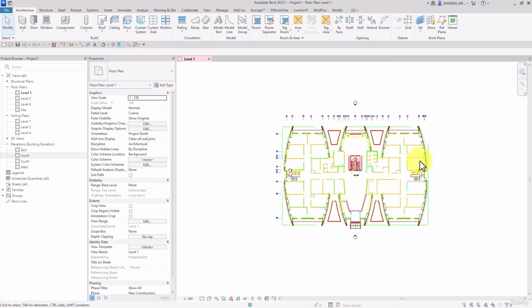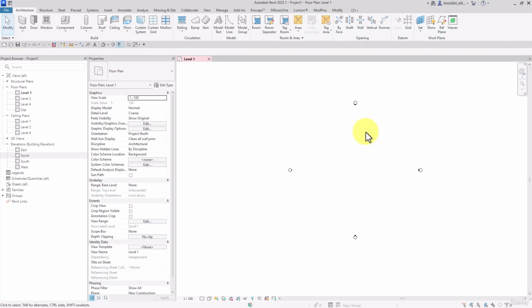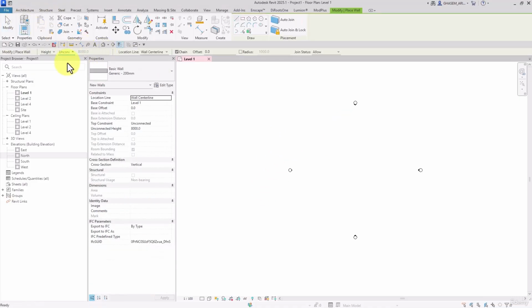Okay, so as we talked about in the previous sessions, the lines were not aligned and the plan was visible in all of the views. But what is the usage of current view only here? Actually, we check current view only especially when we want to add some 2D draftings into a view and then present them in callouts or in the section views. Just the example that I talked about in the previous session.